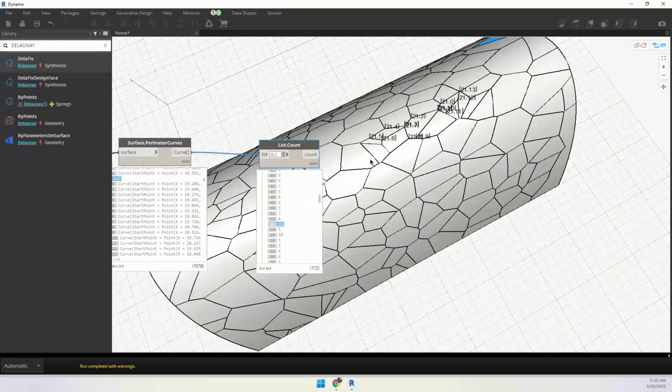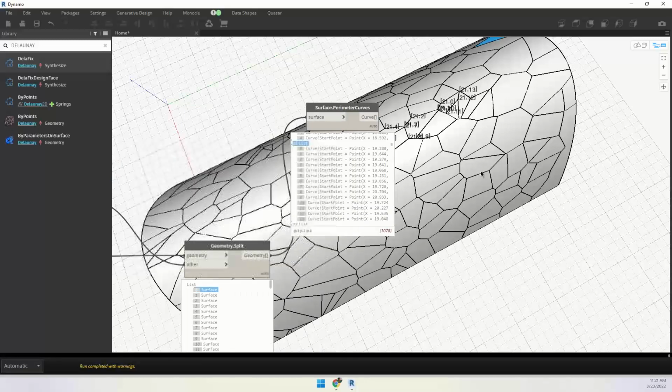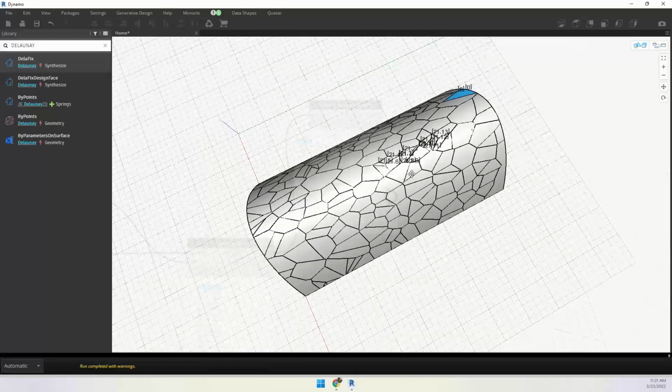Based on this, you have to create a point-based element structure, an adaptive family, which can accept n number of points, whatever it is. It must be closed. If you have that adaptive family, you can adapt this surface with that family itself. Clear, guys?